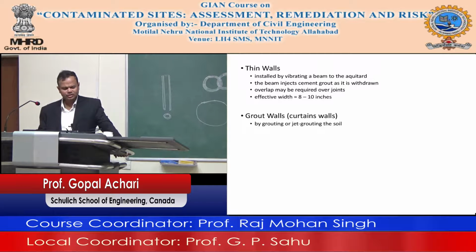The reason you want this leachate collection system here is you don't want water to build up. So the real protection comes from these two, the HDPE liner and the clay. All the liquid that is generated in a landfill is called leachate, and you don't want that to build up here, because it builds up slowly and will make its way down.